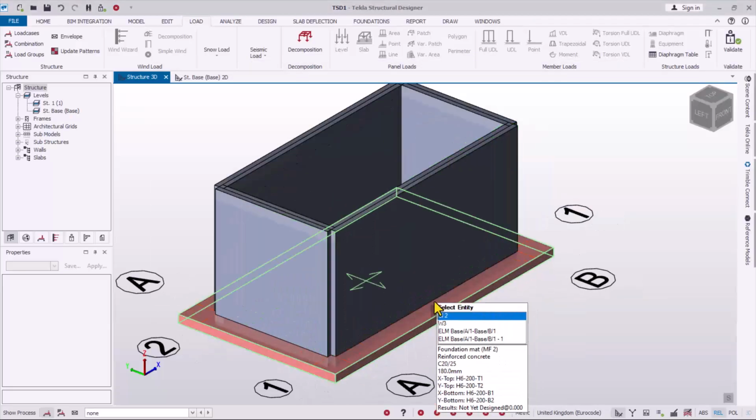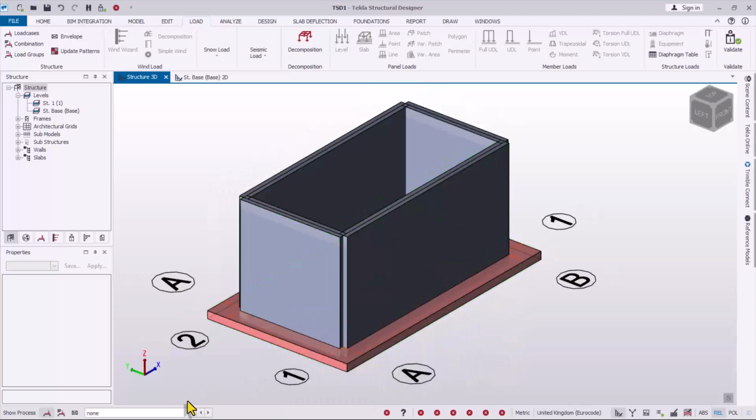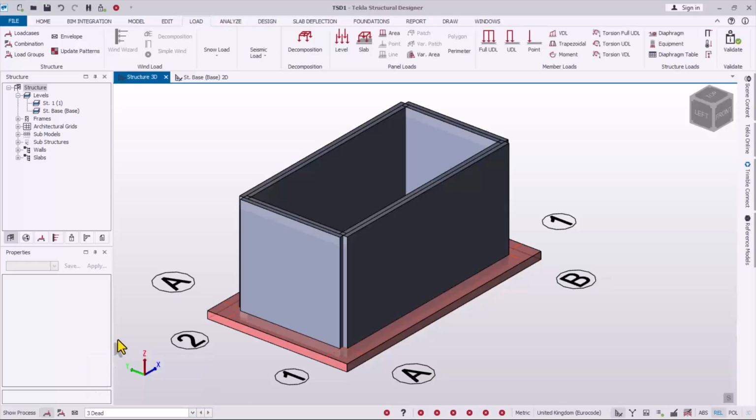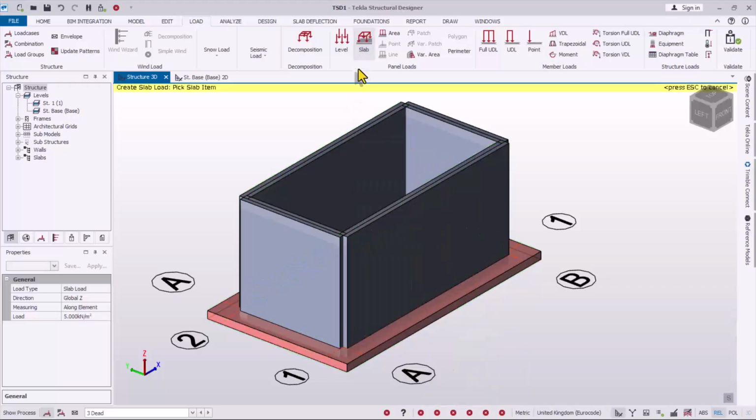Everything is good. Now we want to start to apply these loads on this swimming pool. For us to do that, you just click in these provisions and then enable the load that you wish to apply. I'll select this dead load. It's going to be a slab load, which is going to be on the mat foundation. This is going to be a load due to surcharge. I click on this, and then I will have the value of the load to be this.